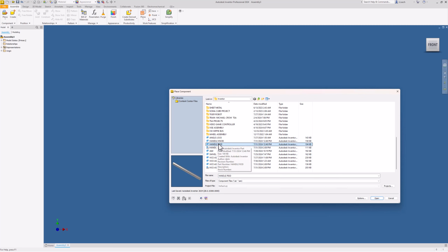So what I want to do now is constrain these planes that I turned on. Let me just use one of these mates. I'm going to click on this plane and this plane, hit apply, then click on this plane and this little short plane here. Click on apply. So now those can't rotate anywhere. And then I'm going to turn off the visibility of these planes that I have showing. There we go.